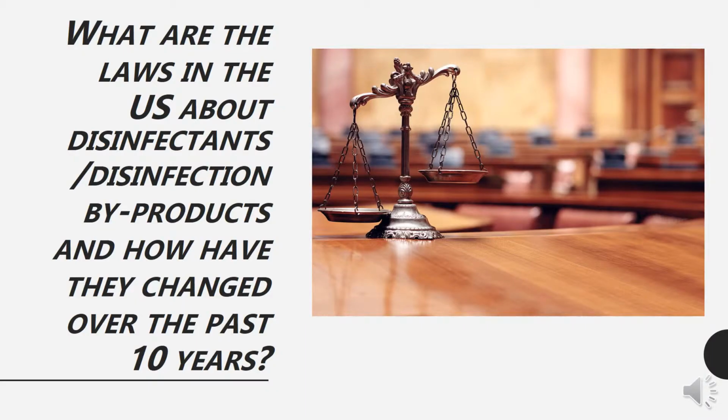As of 2019, only 11 of the approximately 700 disinfection byproducts, or DBP, species that have been identified are regulated by the U.S. Environmental Protection Agency. 4 of these DBPs belong to the trihalomethane group, 5 are haloacetic acids, and the final 2 are bromate and chlorate.